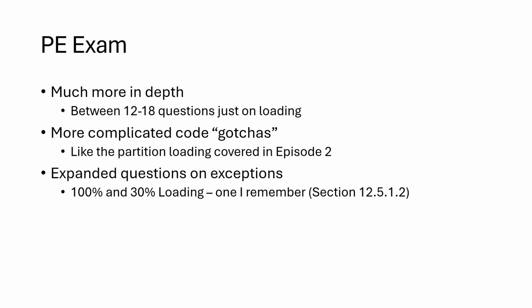So you actually have 130% of your lateral force in an area, depending on the building geometry and some other direction of loading procedures, again outlined in ASCE 7, chapter 12.5.